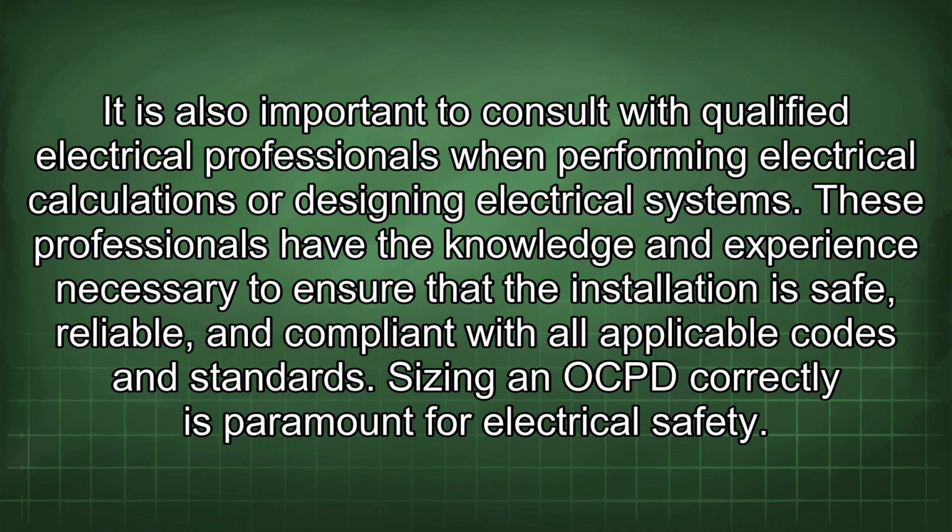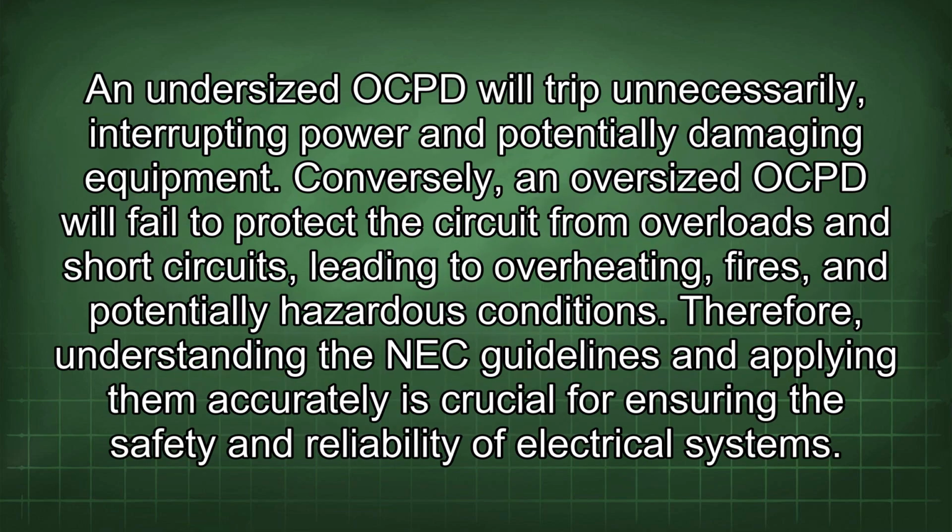Sizing an OCPD correctly is paramount for electrical safety. An undersized OCPD will trip unnecessarily, interrupting power and potentially damaging equipment. Conversely, an oversized OCPD will fail to protect the circuit from overloads and short circuits, leading to overheating, fires, and potentially hazardous conditions. Therefore, understanding the NEC guidelines and applying them accurately is crucial for ensuring the safety and reliability of electrical systems.